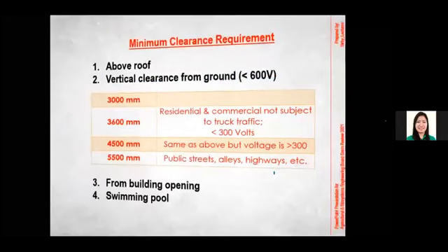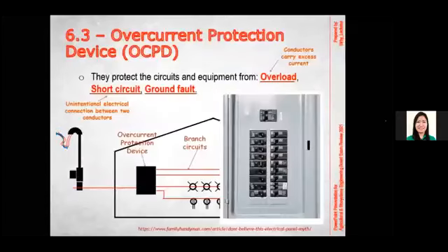Okay, next, we are done with this, right? This is our service drop wire, and this is our masthead, this is our conduit, this is our meter. And from this meter, or some switches right here, there's a line that goes to our final overcurrent protection devices. Okay, so this term right here, that's where the circuit breakers are.